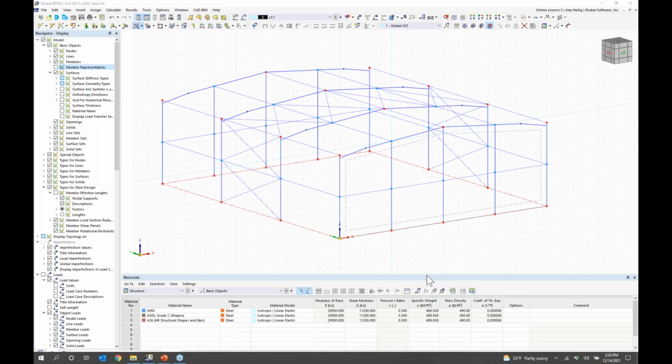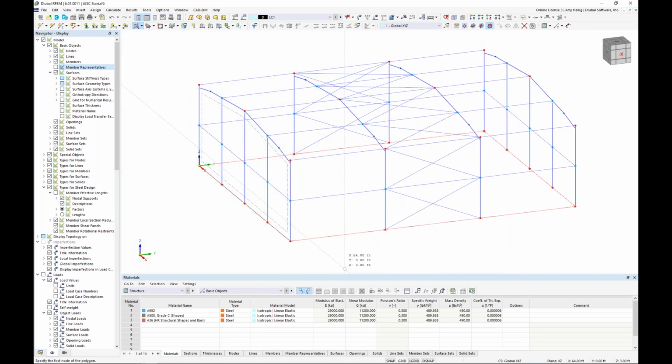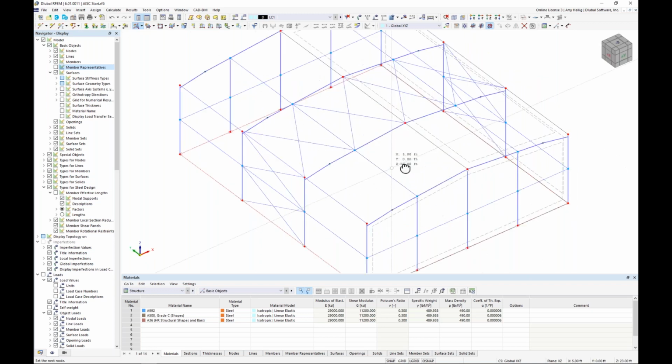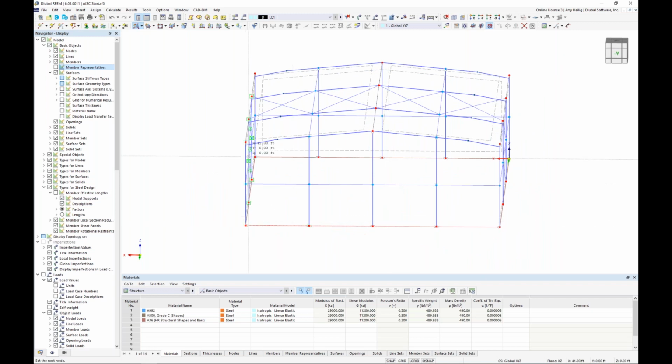And I'll go ahead and turn off my drawing grid here down at the bottom just to make this a little bit easier. Now, currently in a rendered view or a wireframe view, it's a little bit difficult to see these surfaces. You'll notice that only a dotted line is created. And every time I'm closing the surface with that final point, I just double click. We'll go ahead and generate the surface at the left side of the roof here. And then we have one more surface to generate here at the back.